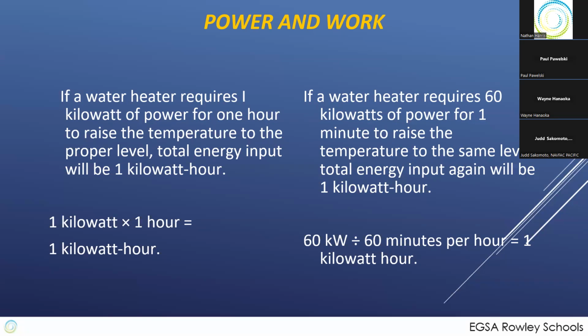And that's why you've got to be careful that if you're sizing something that's using a lot of wattage, you've got the rest of the cabling running to it sized correctly. Because otherwise the cabling is going to get very hot and you will end up using more power, plus create a fire hazard.